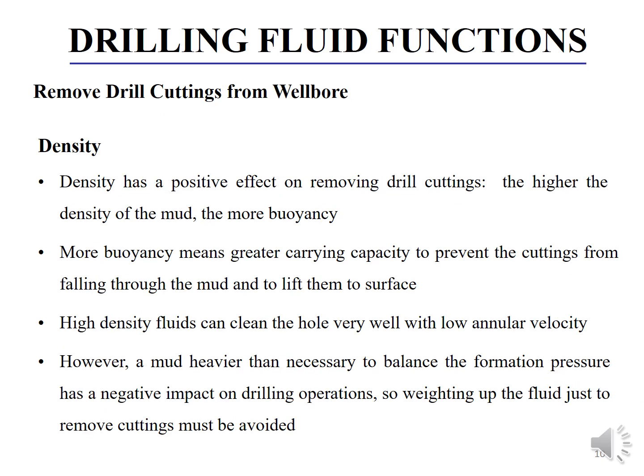Next property is density. Density has a positive effect on removing drill cuttings. The higher the density of the mud, the more the buoyancy. More buoyancy means greater carrying capacity to prevent the cuttings from falling through the mud and to lift them to the surface. High density fluids can clean the hole very well with low annular velocity. So high density fluids are the best suited for lubricating. However, a mud heavier than necessary to balance the formation pressure has a negative impact on drilling operation. So, weighting up the fluid just to remove cuttings must be avoided.